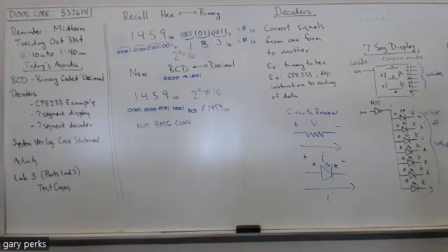Well, this just talks about the 7-segment display. It talks mostly about what I went over. But one other thing on that handout is that it explains that in between this common anode and the input to the 7-segment display, there's this NOT gate. And you might remember that back, I think it was the second meeting we had, I showed you an electronic circuit for a NAND with a transistor, a couple of diodes, and a couple of resistors. Well, you can make an inverter with one transistor. One transistor acting like a switch acts like a NOT gate.